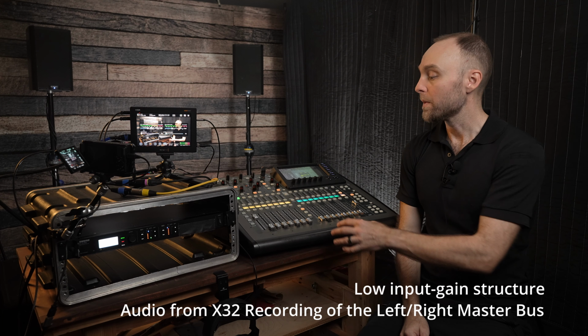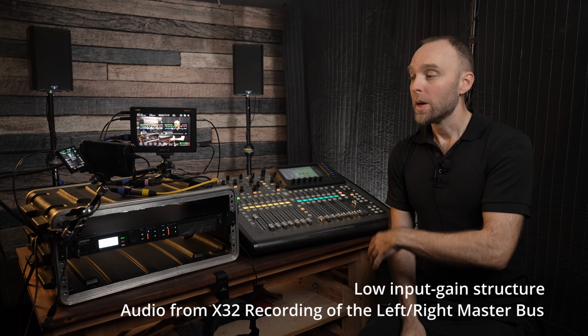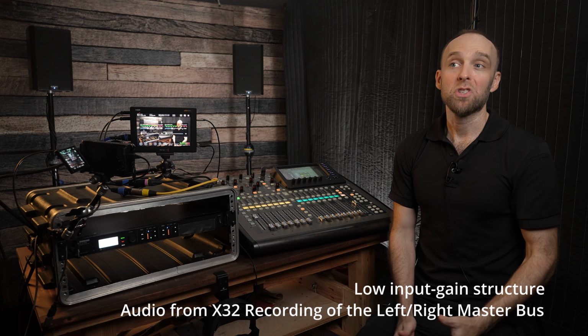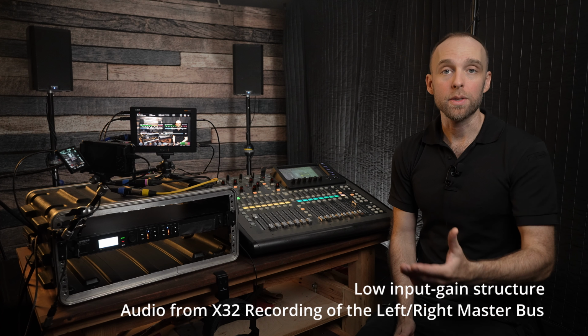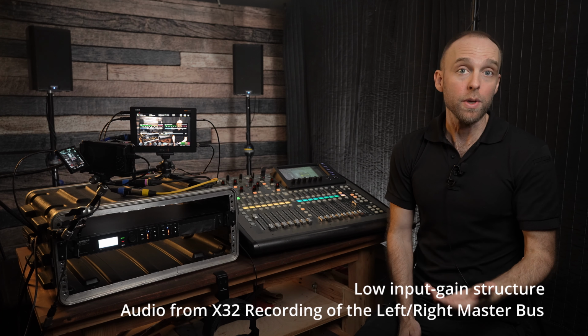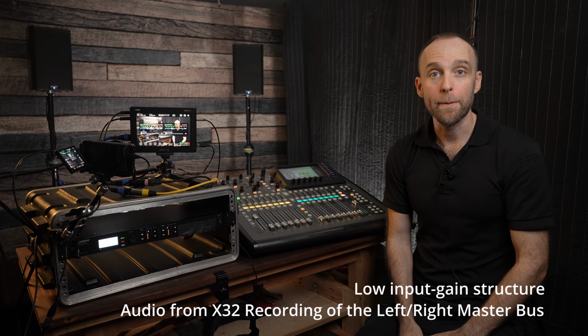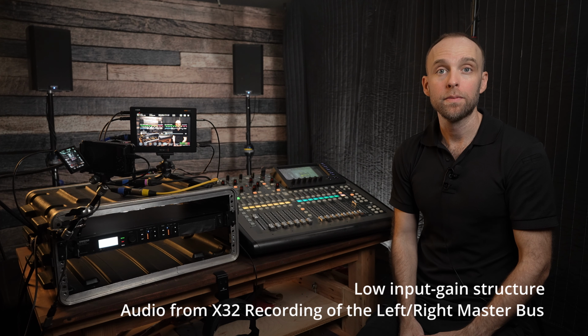Here's a recording off of the left-right mix bus of the Behringer X32 console when I've gain structured poorly. Check, check, 1, 2. I've had to boost this in post so that you can actually hear my voice, but you can also hear the system noise that came with it when I had to boost in post. Here's with poor gain structure.